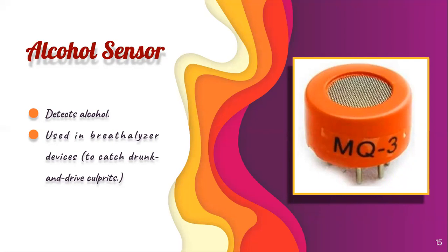There are different types of alcohol sensors like MQ2, MQ3, MQ4, MQ5, etc. Out of these, MQ3 is one of the most commonly used sensors in the MQ sensor series. It is a metal oxide semiconductor type of sensor. It has a good change of resistance of sensing materials when exposed to alcohol. So, by placing it in a simple voltage divider network, alcohol concentration can be detected. MQ3 alcohol sensor works on 5 volt DC and draws around 800 milliwatt. It detects alcohol concentrations anywhere from 25 to 500 ppm.